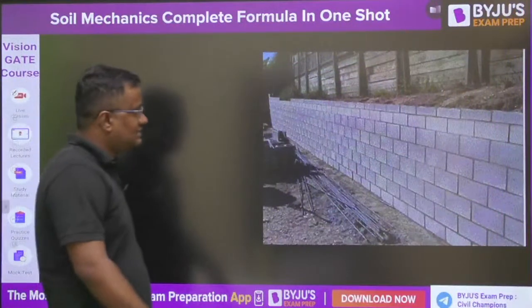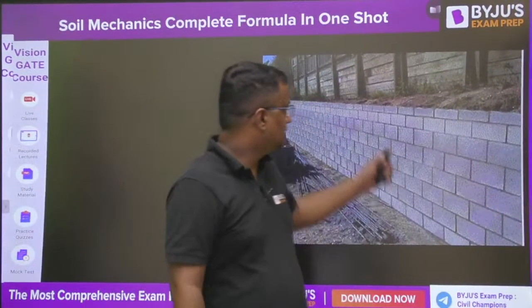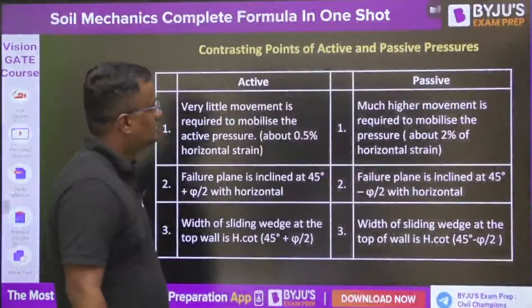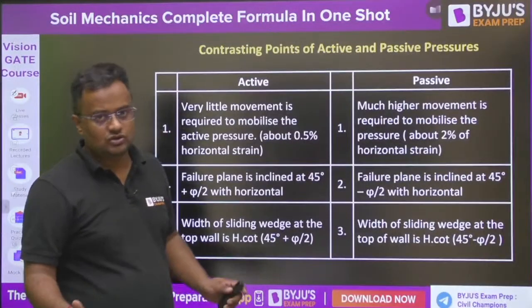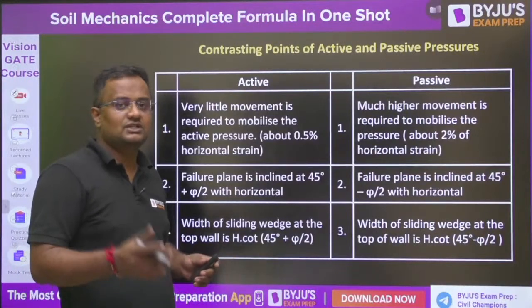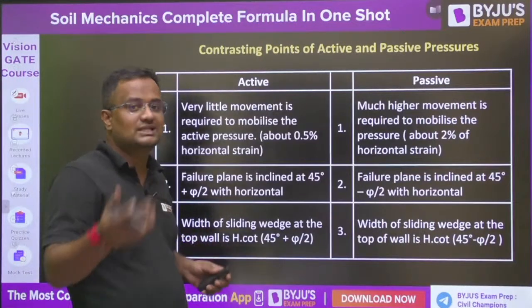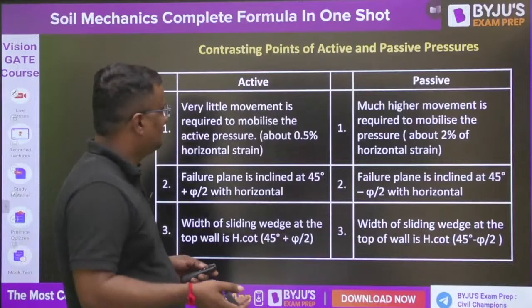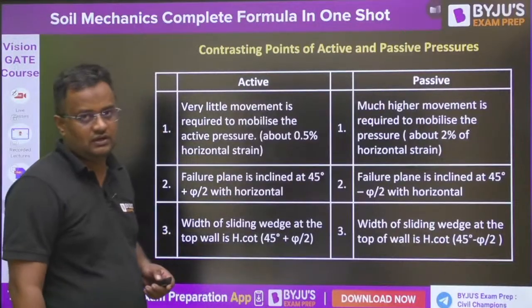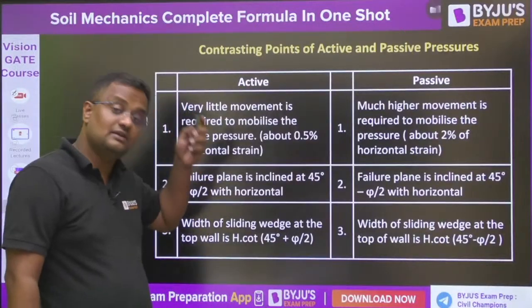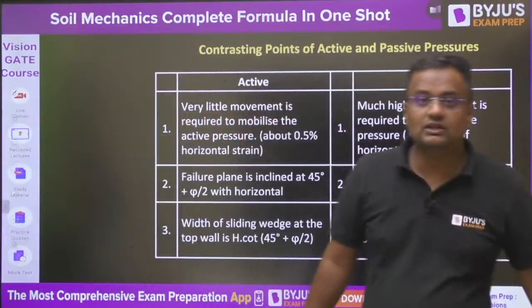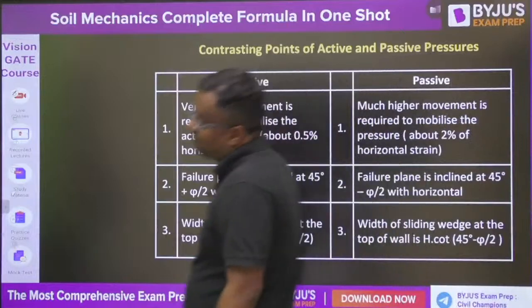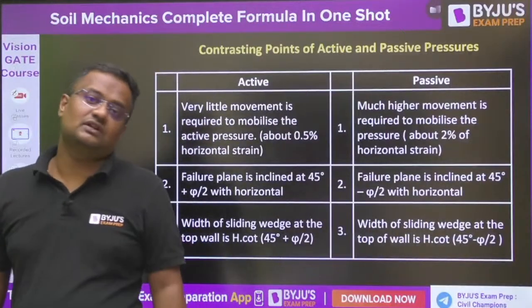Now guys, the retaining wall. These are the retaining walls, guys, and there are three conditions. One is rest condition, when the retaining wall is not moving anywhere. Active condition, when the wall is moving away from the soil, and passive condition, when the wall is moving towards the soil.